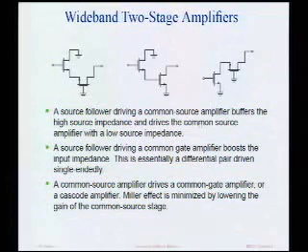And the way I fix my problem is, you might say, well, you still have a Miller capacitance here, but I've reduced the voltage gain on the first stage, right? What's the voltage gain of the first stage? Yeah, 1 if the devices are sized equally, -1 to be more exact. So the Miller multiplier factor is only 2, right? So the capacitance doubles, which is not too bad, right? As opposed to getting 10 times bigger in the common source amplifier.